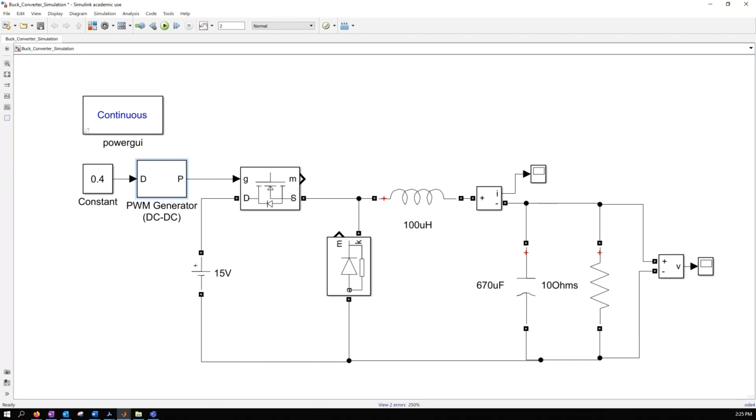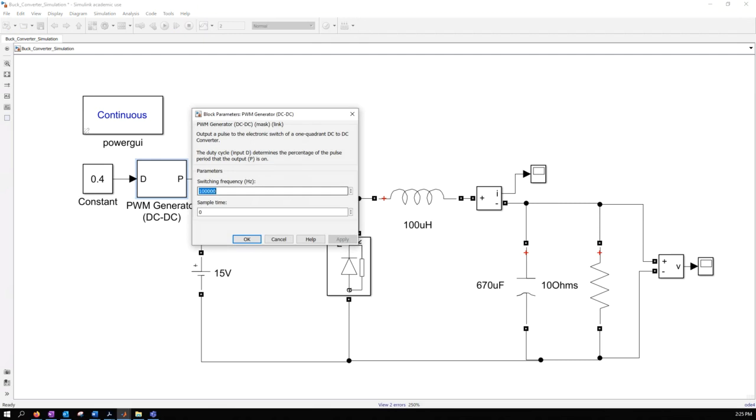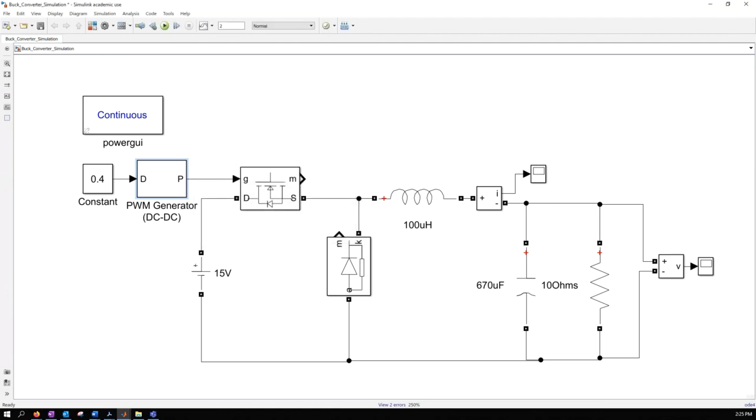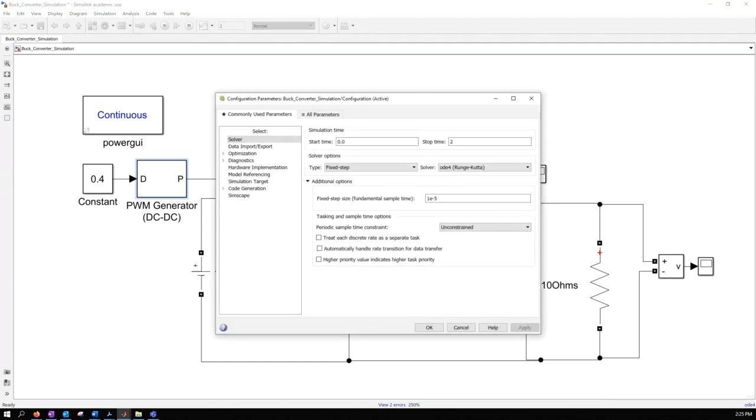All right. So since we want our Simulink model to run at a 1e-5 period, or this PWM frequency is at 100 kilohertz, right? That means a 1e-5 period. We need to have more data points within that one PWM interval. Therefore, what we're going to do is go back here and say, since we are running fixed step, we're going to make this step size much smaller.